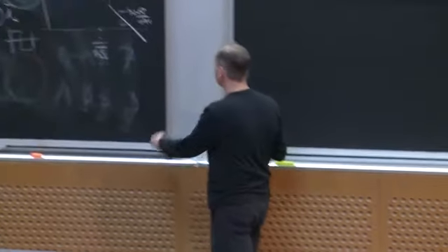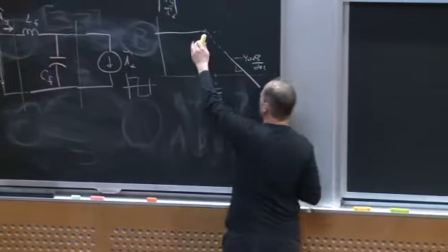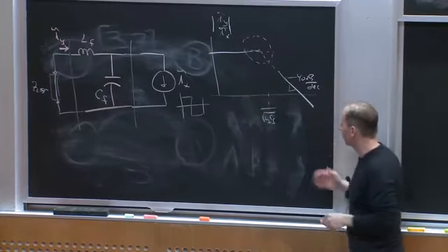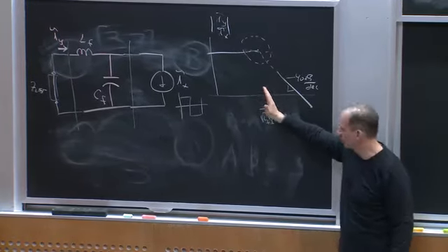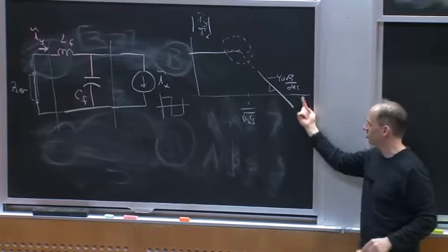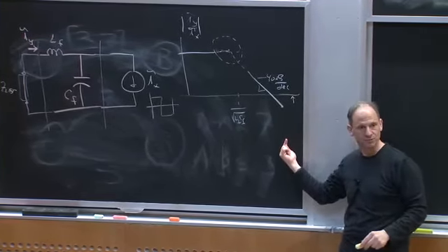And that's great, and I'm intentionally ignoring what happens in the vicinity of cutoff, because keep in mind, the cutoff is at some low frequency, and we're going to put our PWM frequency and ripple frequency way out here somewhere, so we're getting lots of attenuation. Okay?